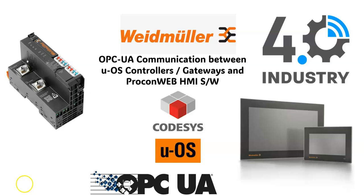Today I'd like to talk about OPC-UA communications between Weidmuller's range of controllers or gateways and ProconWeb HMI SCADA. Just as a bit of background, if you're not familiar, Weidmuller controllers use Codesys. The Weidmuller controller is a Linux-based PC running a soft PLC version of Codesys on board. UOS is the term given to the Codesys-based controllers in the Weidmuller range, and ProconWeb is the name of the software package we use with our HMIs and controllers.